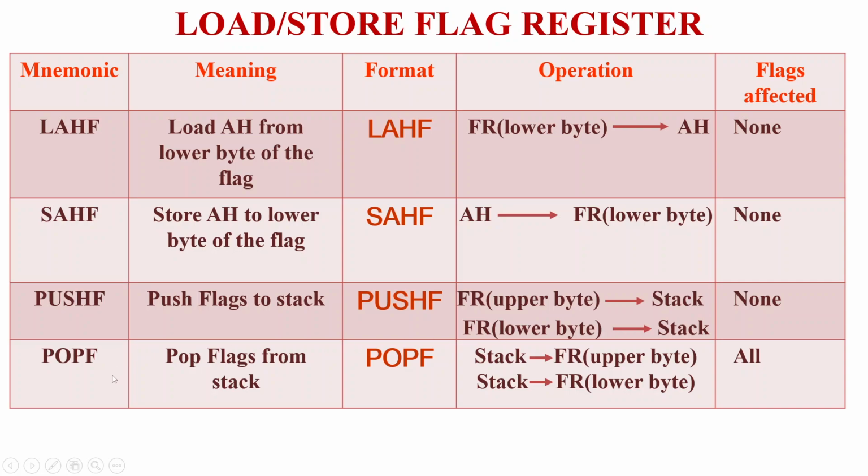And the last one we are going to discuss is POPF. Pop flags from the stack. You are going to take the flags from the stack. So when I say the format is POPF, when this instruction is executed, the content of the stack is moved to the upper byte of the flag register followed by the lower byte of the flag register.